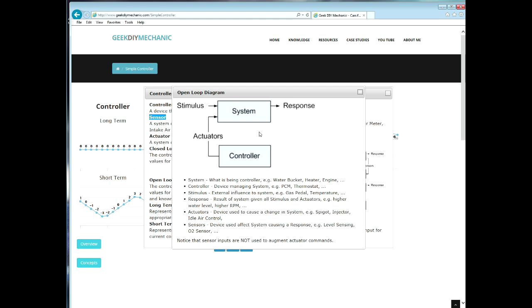How that relates to a car is your fuel system is in open loop until your O2 sensors warm up. When they're warm is when they can sense the oxygen, or the modern air fuel sensors can detect the air fuel ratio in the exhaust gas to tell the computer so it can adjust. But that's beyond the scope of this discussion. I just wanted to give an example why I need to discuss open loop in cars.